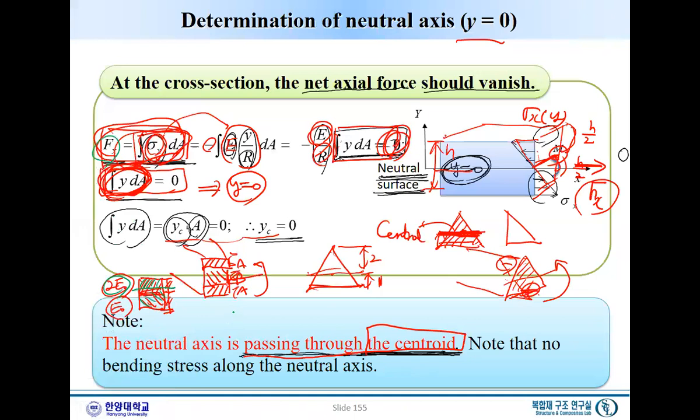See, one thing very important is that regardless of this multi-material stack, no matter how many materials, no matter one material we have, epsilon x is always proportional to y d theta dx. Always linear.